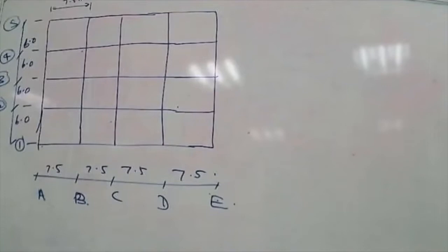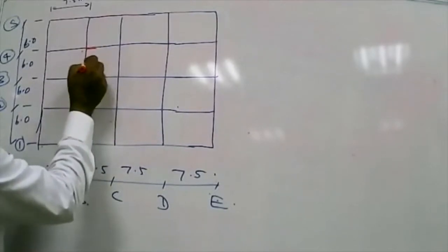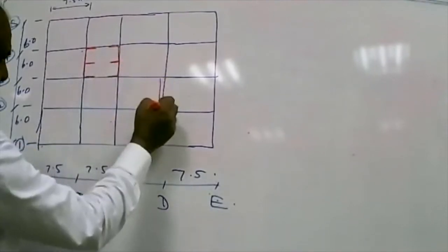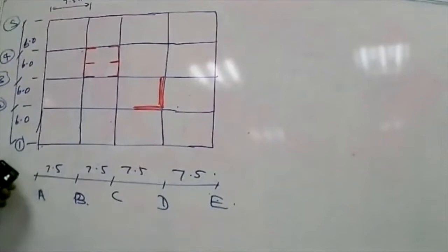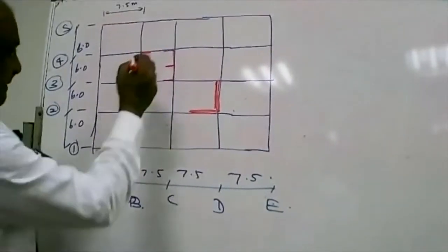If it's a 10-story building, generally we allocate about 25% of the area for the service core. So I'm planning to get a lift arrangement like this. And I will have another wall here, another wall here. So these are lifts.